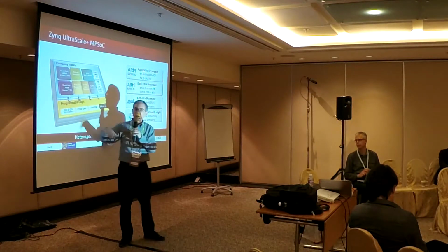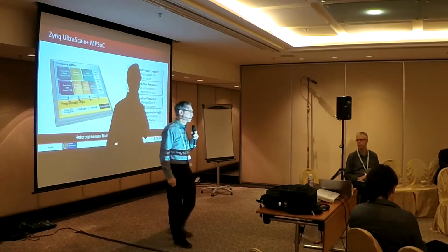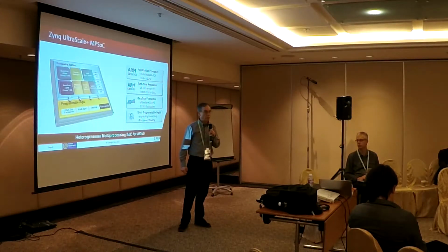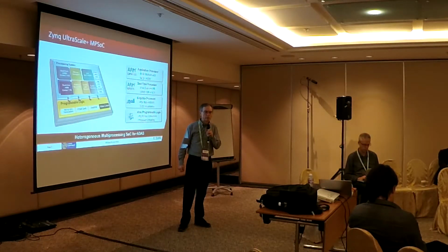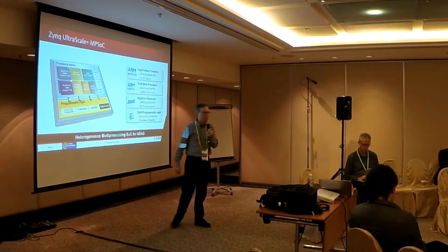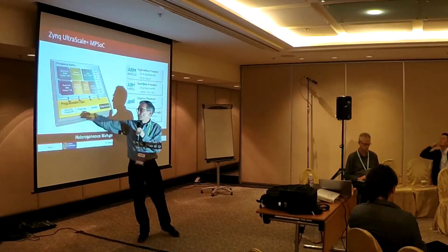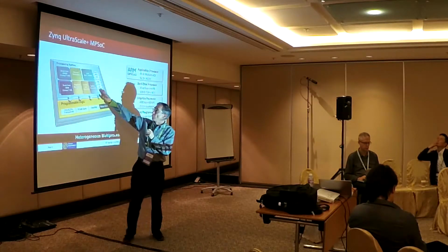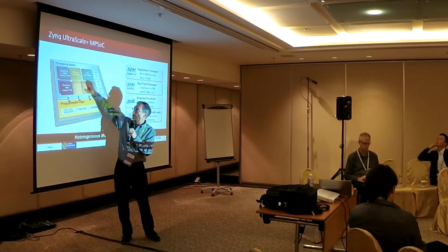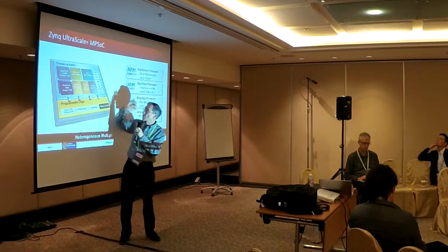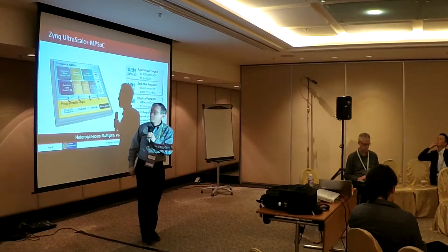We have a lot of high-speed serial transceivers, very valuable for things like PCI Express, as well as other industry standards for high-speed communication, especially in backplanes of servers. Some of our devices have PCI Express Gen 4. Within the actual processing system, we have all these peripherals. You'll also see PCI Express Gen 1, Gen 2 there.